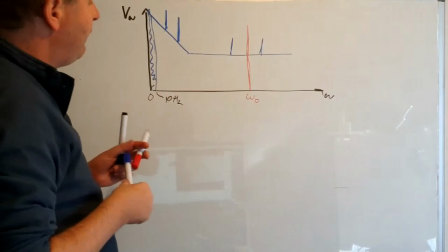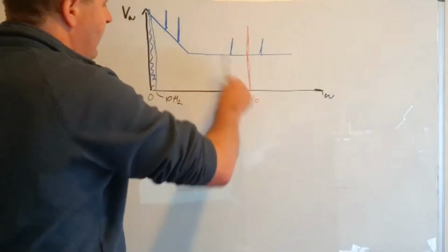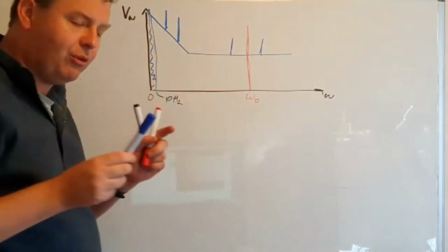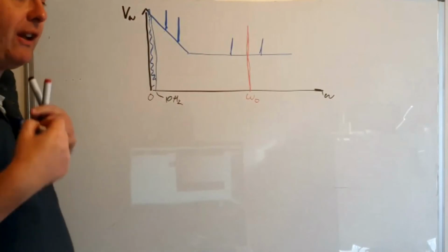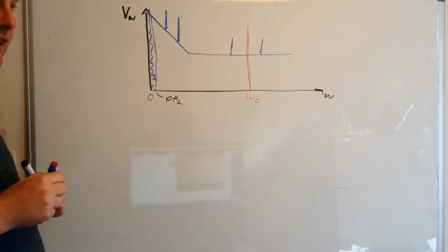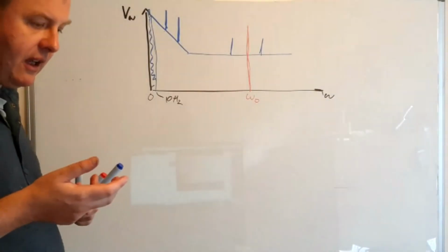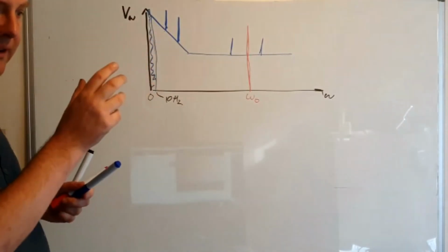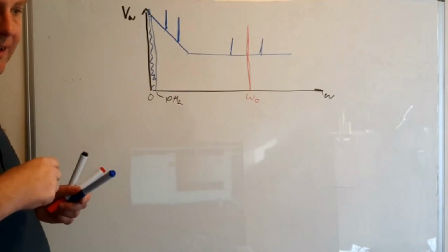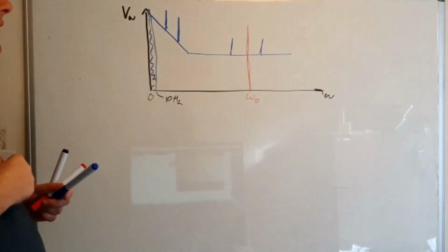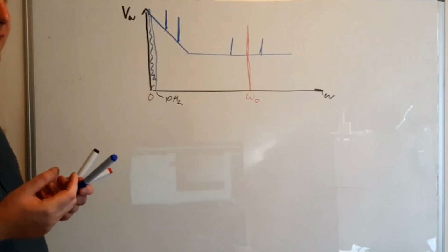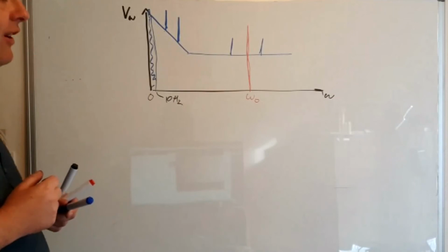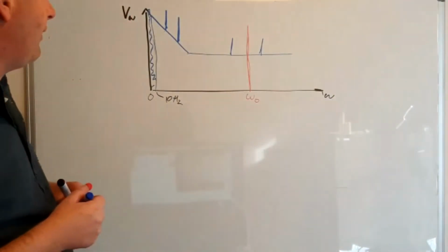And what we're effectively doing is saying, okay, let's just measure in this range, and let's go and measure just precisely at our omega naught. And what's controlling how precisely we're measuring at omega naught is how long we're going to average our signal for, because that tells us, back in that expression from when you calculated the effect of averaging, right at the end, there was that term which went as cos (omega_i t minus omega naught). The longer you average for, the closer omega_i and omega naught can be, you can still average away that cosine term. So that's what's controlling how much we're actually measuring.